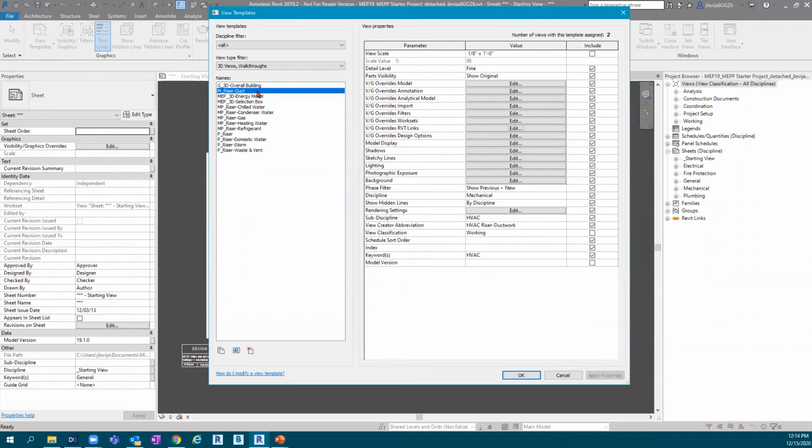I'll do this as a riser duct overall. And then I'll also separate out my separate categories as well, because I like to do my own internal clash detection also, especially at the beginning stages of a project when maybe we're still estimating the project, or maybe we're trying to just kind of see what quality the design model has come to us in. So that way we can start heading off issues if we have to put out an RFI, or if we have to do some more design or even more modeling to kind of catch up. So that gives us some flexibility there. As I go down a little bit further, you can see here I've got some of my MEP drawings.